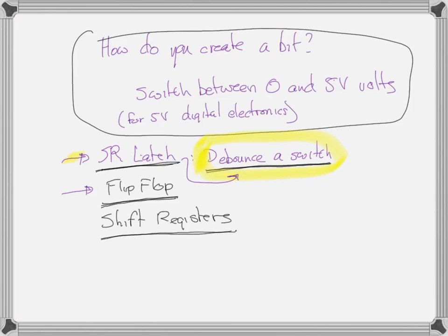What that means is you put in the information and it reads it, and it determines its next state. Okay, so let me say that a little bit more clearly. An SR latch is a memory bit. You can set its state, and it's going to remember its state, and you can change its state by putting in more information. So its next state is going to be determined by what its current state is and what the new information you send it is. And that's just going to happen when you put the information in.